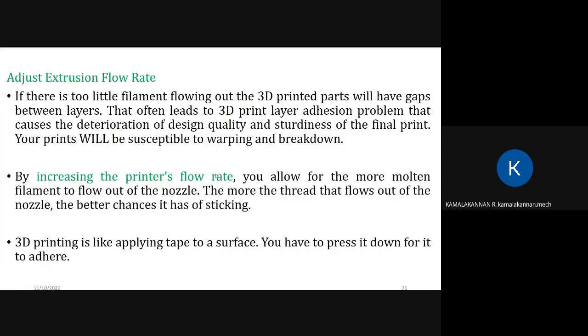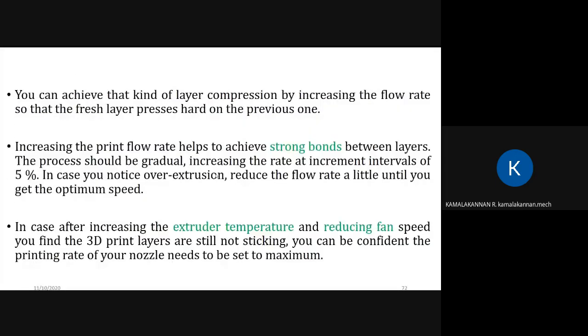Then increasing the print flow rate helps to achieve strong bonds. You can increase the flow rate by a certain level. You cannot go more than that because of the size of the nozzle. So you will have a proper flow rate depending upon the size of the nozzle. So you have to choose accordingly.